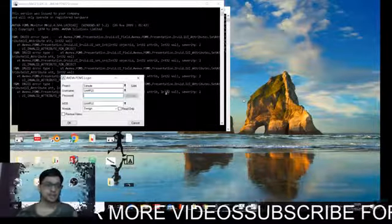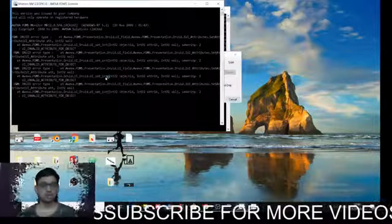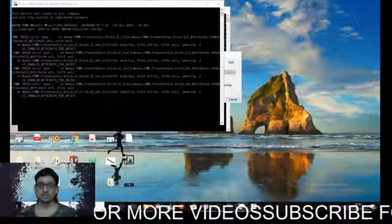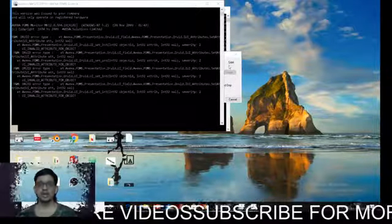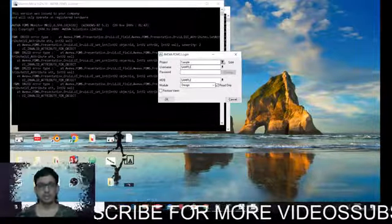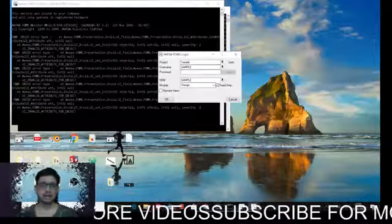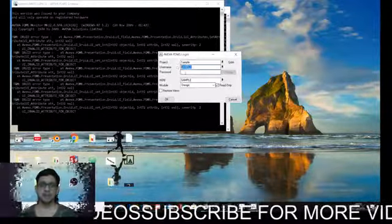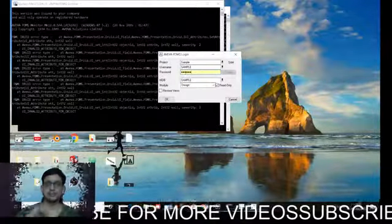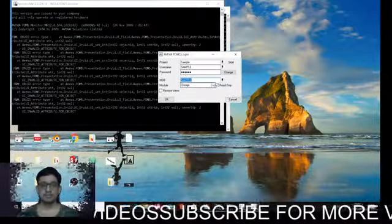Now this is the PDMS login window which you get. If you have a server, you can always go with the actual username and password. We are using a standalone system here, so we will be logging in using sample. Everything will be sample. You can select a project name if you want. We will be starting with the sample project. We will use the username as sample and the password as capital SAMPLE. Enter that, and then we will go for the module.